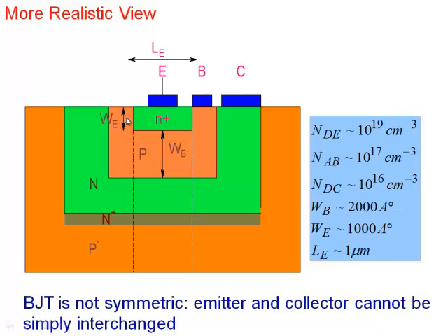Its thickness, note, thickness is pretty thin, maybe 1000 angstrom. As I said, these are typical values. It could be 2000 angstrom, it could be less. So 1000 angstrom, just to give you an idea of the order of magnitude. So emitter is heavily doped and thin. Base that you see here, all this P region here, base, say a doping of 10 to the power 17. We also try to keep this base thickness that you see here as thin as possible. The transistor speed and current gain and all that depend on the base thickness here. And so that's the base here, 10 to the power 17.